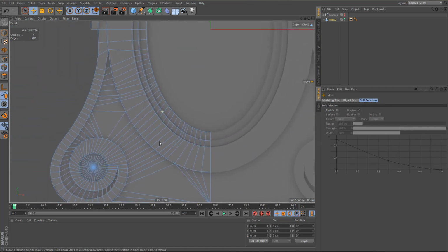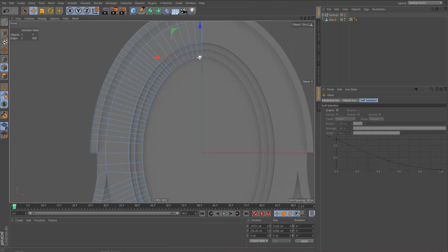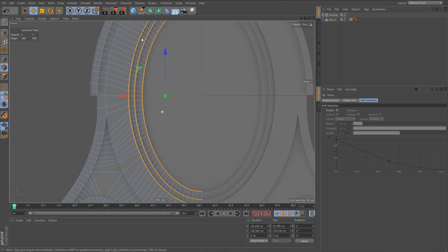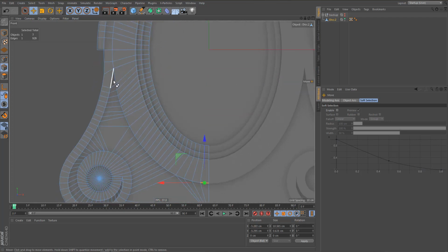So I just added 2 more edge loops, which means that up here I'm going to select 10 edge rings. So that's 4, 5, 6, 7, 8, 9, 10. And I'll just connect these. And now, hopefully, when I run that script, I get a pretty even distribution of the edges here. And down here, I'm just going to run that script on these edges here.